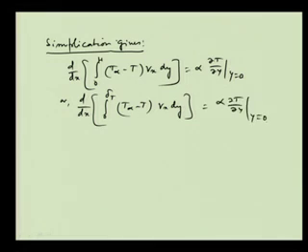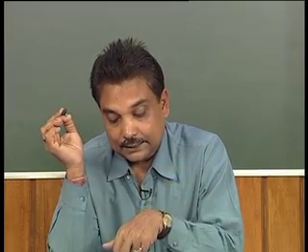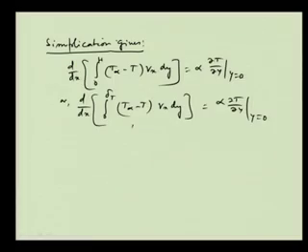We have replaced the upper boundary h by delta t, because delta t is lower than delta, and after delta t the term T infinity minus T vanishes. So there is no use of that part of the integral, and we write 0 to delta t. This equation is called the energy integral equation.